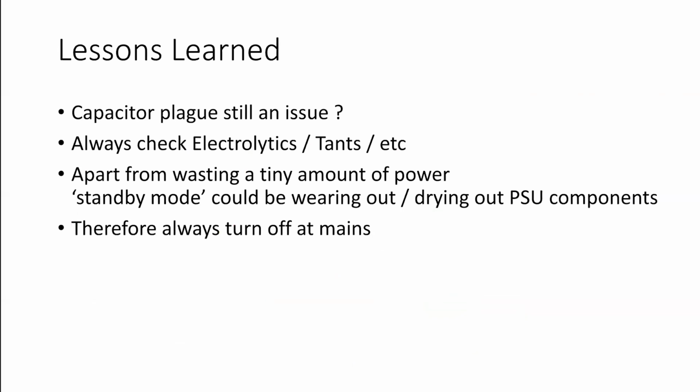So, lessons learned. Capacitor plague from 20 years ago is still an issue because there are still capacitors from 2001 turning up in equipment. If you open a piece of equipment and it's dead, always look carefully at electrolytics and tantalums and other dubious capacitors.